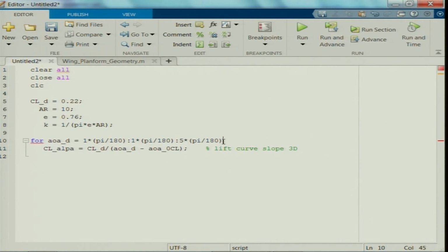You can choose it to be 0.5 or even less than that. Okay. So, this is how typical design angle of attack, within this range, because L by D maximum for typical airfoils will also fall within this range, maybe up to 7 degrees. And CL alpha from here depends upon AOA, right, and then alpha at which CL is equal to 0.